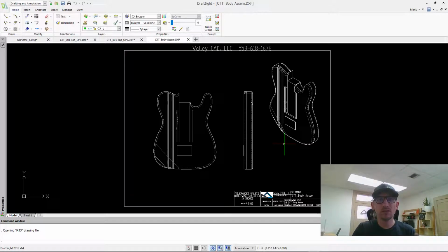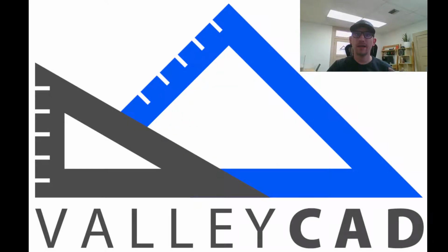Okay, so these are 3 ways to be able to make a DXF/DWG file from SOLIDWORKS. Okay, so the one that I generally use is from a part file, right click on the body, export to DXF/DWG, and specify what faces or edges I want to export. When you have a part file that has faces that are not planar, you will want to use the annotations form, and that will allow you to export. If your body's on a front view, you'll export everything that sees on that front view. You can also export more than one view at one time if you'd like.